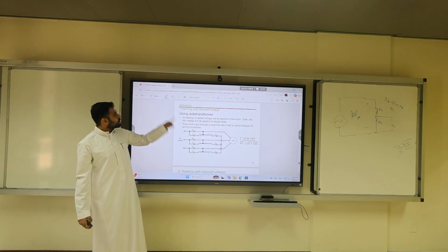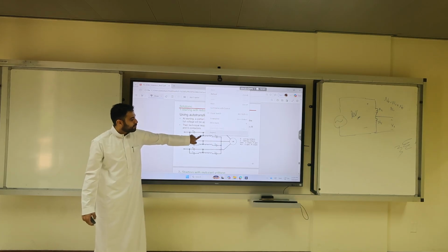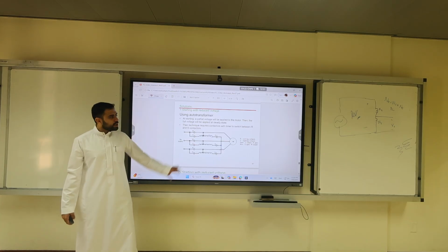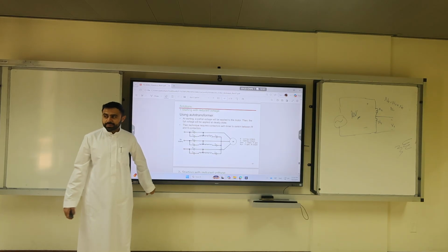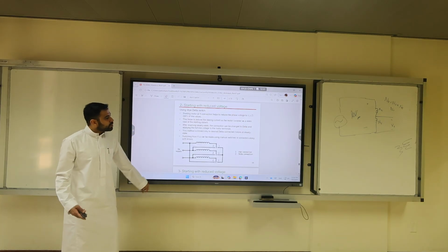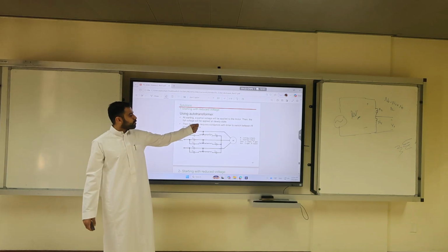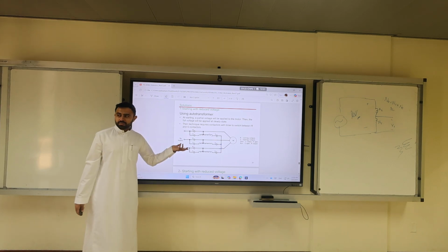Usually the tap changing transformer comes with an arrow. They put an arrow for you, meaning there is more than one level. So here we're making it simple; we're using a fixed auto transformer. Let's read the text a little bit. Partial voltage will be applied, then full voltage will be applied at steady state. The technique requires contactors with timers. This is old school. Okay?